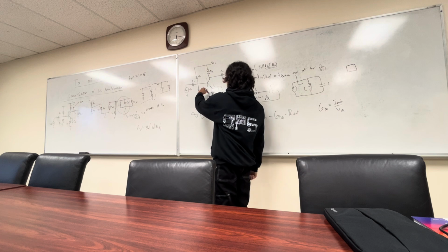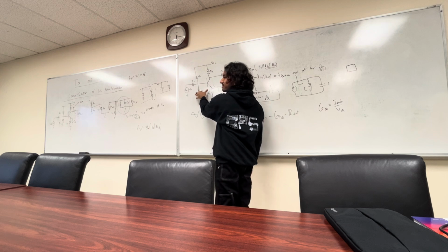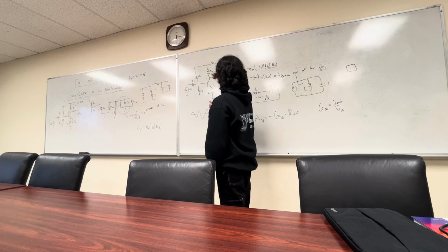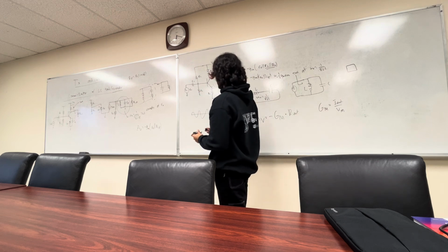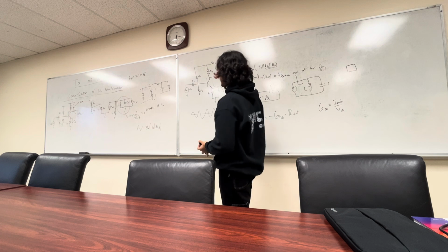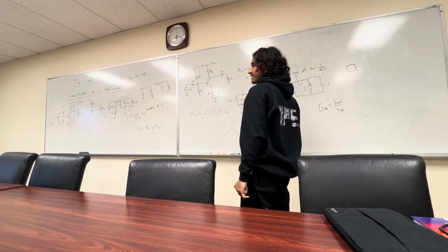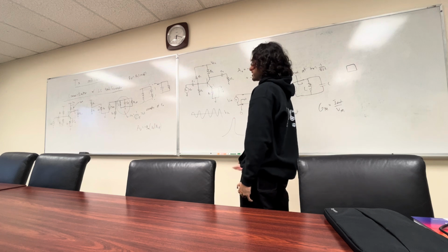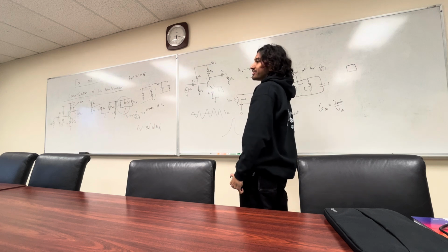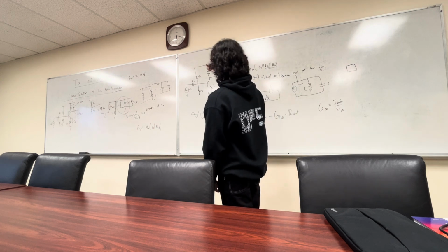We have physical material here. The trace is already contacts, it's wires. But even though there's no direct path for conduction, you can still see some effects. Is that very noticeable at these frequencies? Not really. But at higher frequencies, it's very easy to accidentally make an oscillator. The common joke is, you make an amplifier, you get an oscillator; you make an oscillator, you can't get it to oscillate, so it just becomes an amplifier. That happens all the time.